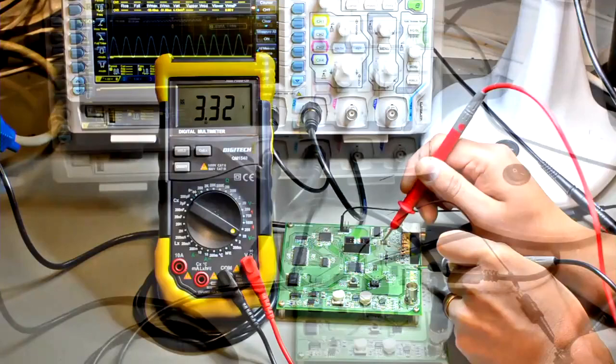When you got the PCB, without mounting the components, what did you do first? Testing? Power? When you get a bare PCB, as a system engineer, what you should be testing is: take the multimeter, connect it to +5 and ground to make sure that it is not shorted before mounting the components. Otherwise, after mounting the components, you don't know whether the short was there at the beginning or whether it got shorted when you soldered.